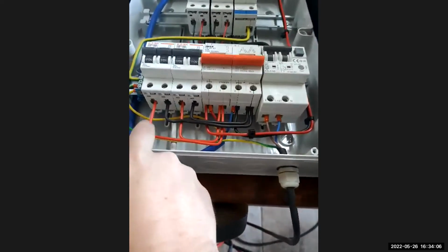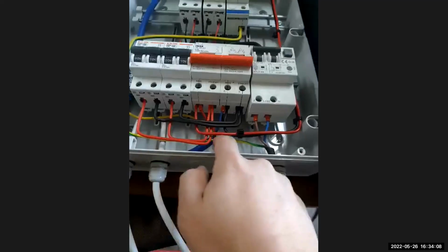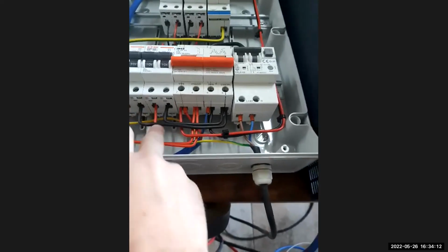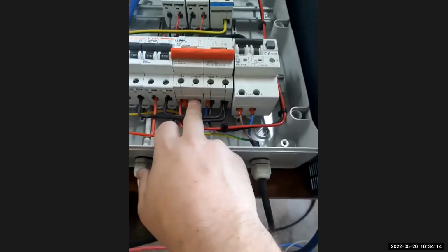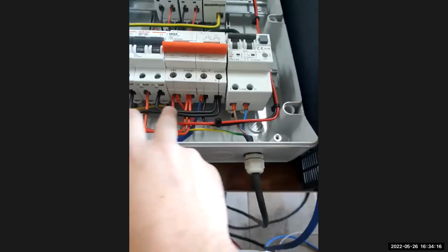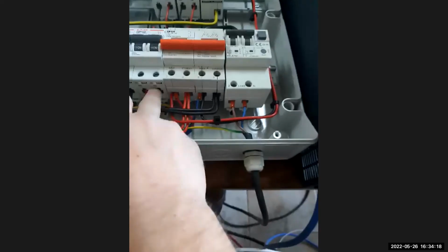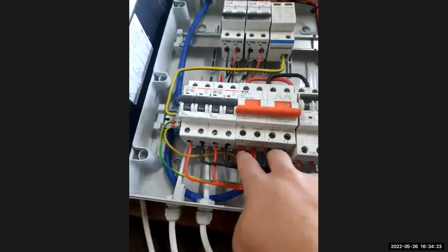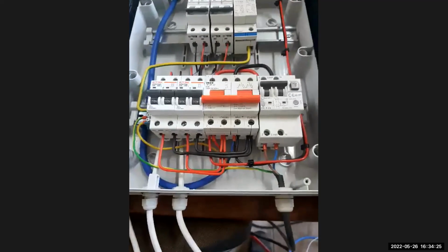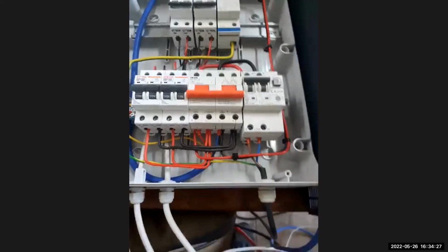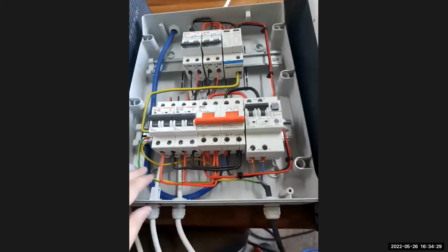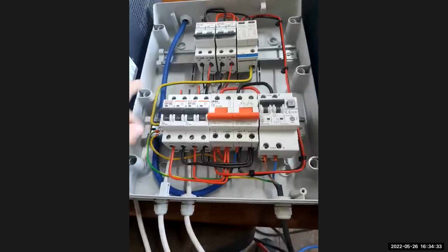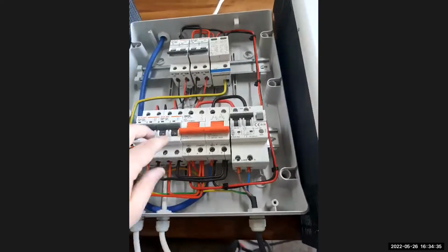The output of my first inverter's breaker joins there. Then the output of my second inverter joins there on my live side. Then my neutral side is joined there and my neutral side is joined there. So this is where the two inverters join, where the paralleling happens. I have clients that did this paralleling before the output breakers. That defeats the reason why I have output breakers.